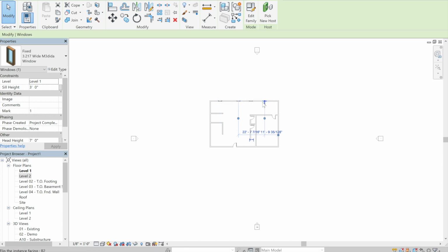and if it doesn't have that family loaded, it's going to create the family. So for example, this window in AutoCAD was 3.217 feet long, okay? And obviously Revit doesn't have that loaded. That's not a native family to Revit. So it ended up finding this family, duplicating it, and then creating this family for you, okay? So that you have your window types and you can easily go through and select and change them later on. So for now, these are just placeholders so that you guys can continue working quickly in your project and meet your deadlines. All right?